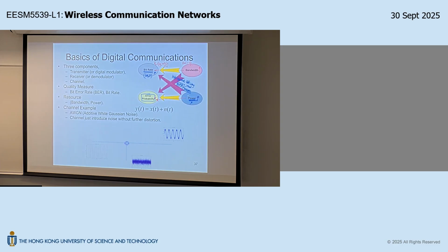So if you express the coordinate of each point using polar coordinates, for example, R theta, right? That means the differences between these points is only the theta part. The R part is the same. Is that okay? So if you go from this point to this point, the only thing that was changed is the theta coordinate, right? So theta is interpreted as a phase. So that's why it's called phase shift keying, because the differences between the signal points are due to the phase term only. Okay? So you're using the phase difference to signal between different input bits combinations.